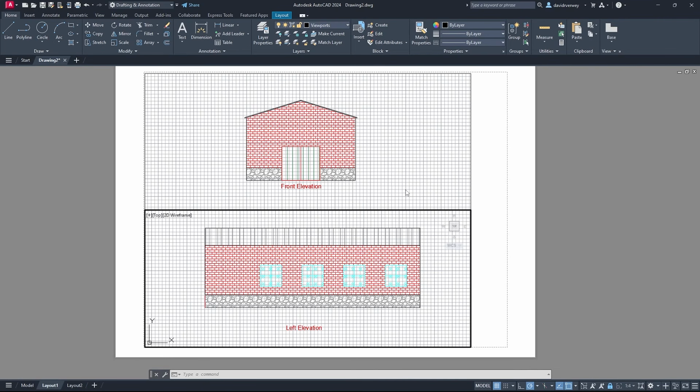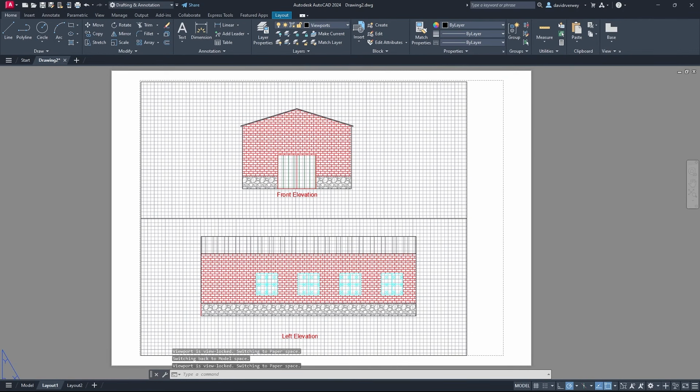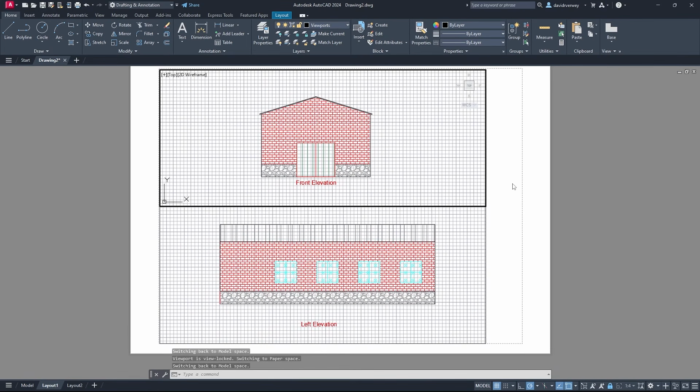So what you can do here is set your paper, set the size and everything. We're just dealing with the basic size of the paper right now, and it lets you see what it would look like on the sheet of paper. Now you're going to see there's this dotted line across. You want to keep everything within that dotted line because that's what's within the printer space. That's the size of the paper, and that'll keep you in line, and it'll make sure your drawing shows up properly where it should. So that's pretty much it. Viewports, it's important to know. Again, having a viewport layer is very good to have. It keeps everything concise and clean.